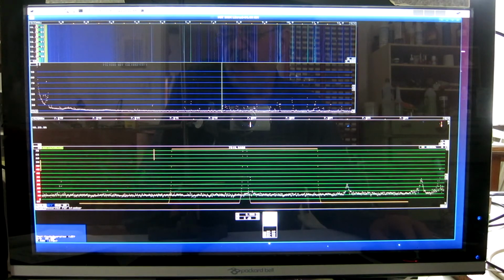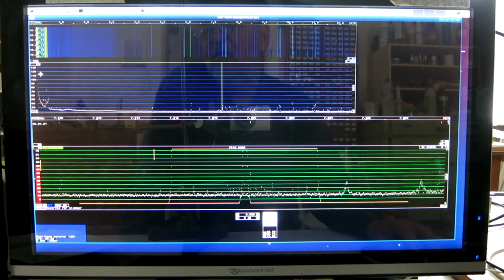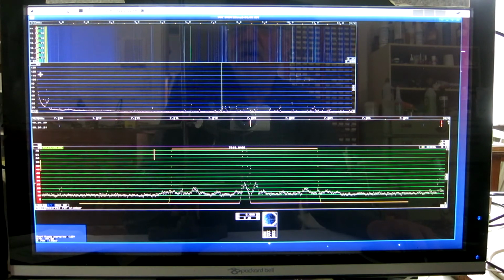The amplitude margin here, 22 decibels only, is the same as at night time. It is caused by the DC component. You can see DC goes all the way up to the top of the scale. I have to click here, and you see the DC component is 103 decibels or something. And that is high above where the signal levels were at night. So the card can accept a significant gain in front of it without going into saturation.